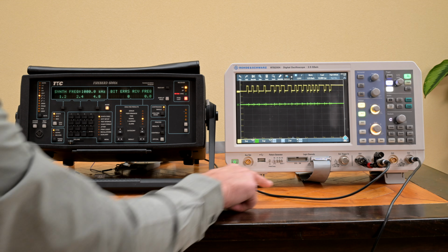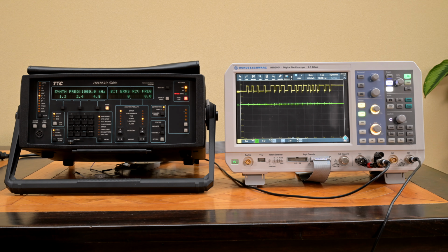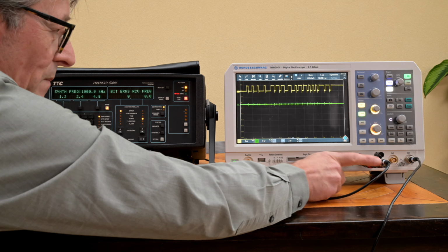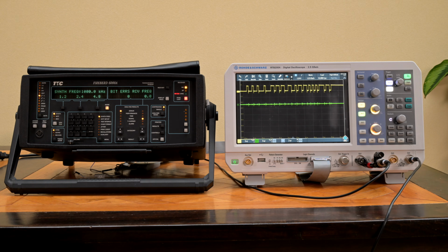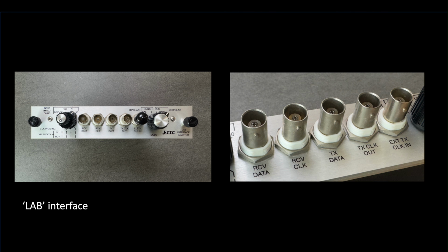As you'll see, I'm not bringing the BNC directly into the scope, but I'm bringing one side into one channel and the other side into the other channel. Because mind you, if we look well at the connector on the lab interface, we will see that this is not a grounded BNC, it is a floating BNC with respect to the frame. And in a moment we will see why this is the case.